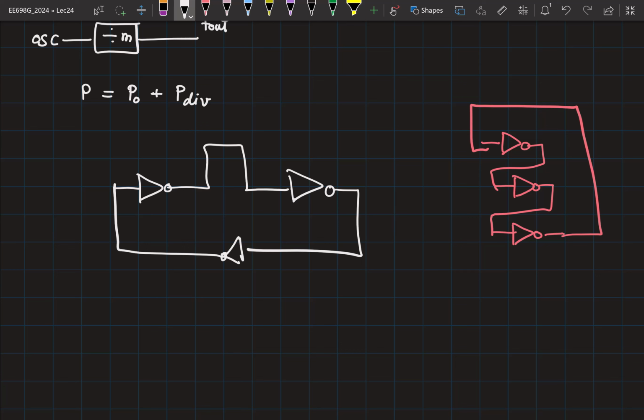Your solution of increasing the routing for in-between nodes was also very valid, but just that you had a longer routing at the bottom, right? So you will additionally increase the routing by a lot. Now in this, the routing you need to add here is going to be slightly smaller. Right? So this way, when you lay out things that need symmetry, you have to be extra careful.